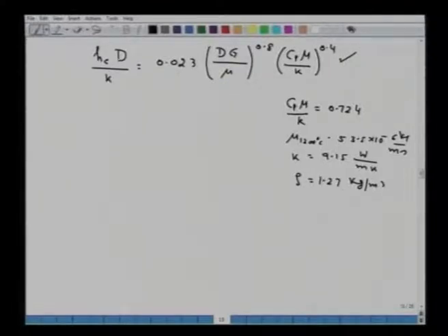There I am giving you the required values. So, if you substitute all these values into this expression, you can calculate Hc, the heat transfer coefficient for convection, that is equal to 8.268 watt per meter square Kelvin. Remember, in A the heat transfer will occur only by convection, because no triatomic gases are present. That is the idea of illustrating this particular problem.